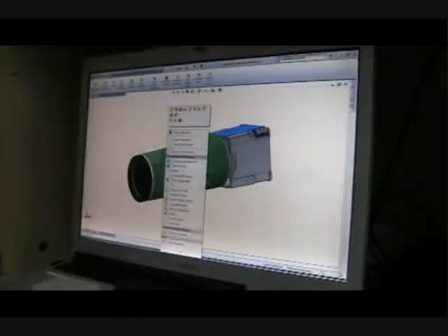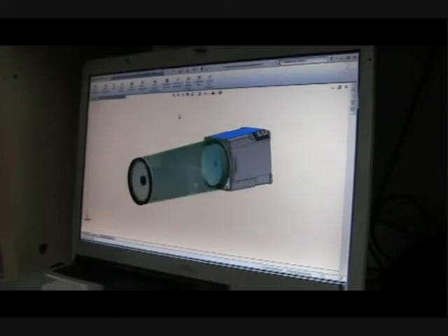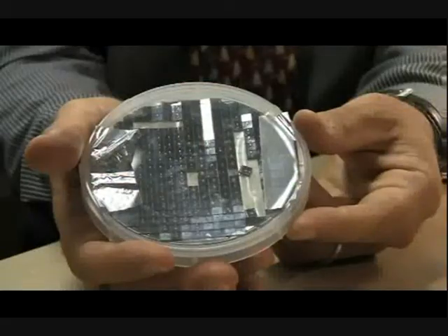And just to talk about the propulsion system, what we need is always a certain amount of fuel on board, and this will be a part of the satellite dedicated as a tank to contain the fuel. And then we will have micro nozzles to perform the function of the rockets, which are positioned in different points of the satellite to create the torques that rotate the satellite, or the forces that move satellites with respect to each other to change distances and positions.